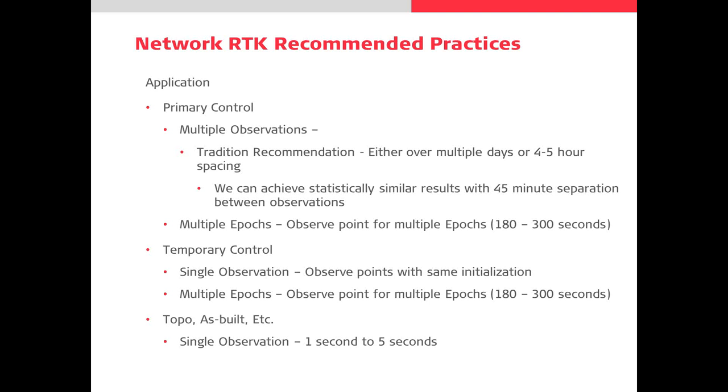Now the good thing I think is that with only a 45-minute separation, I now have the availability to possibly even come back and occupy those 2 points again to be able to tie it in even tighter. That's not necessary, but it could be something you do. For topos, as-builts, etc., I can do a single observation from 1 second and even roll that epoch rate up to 5.